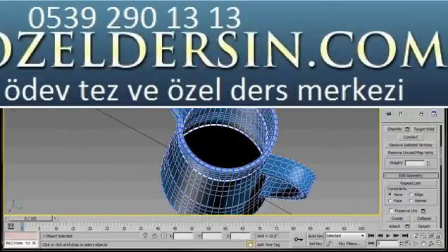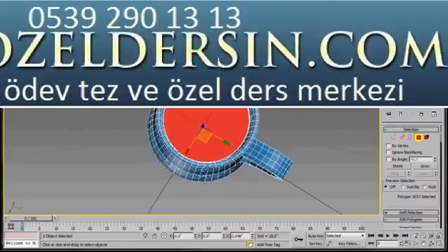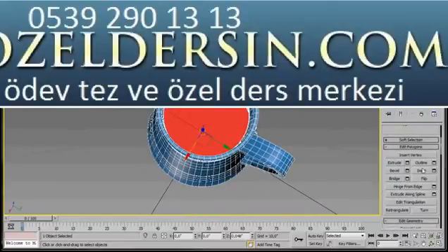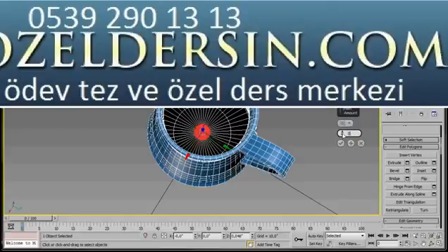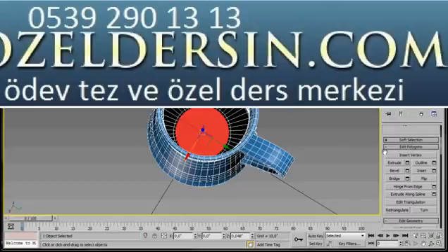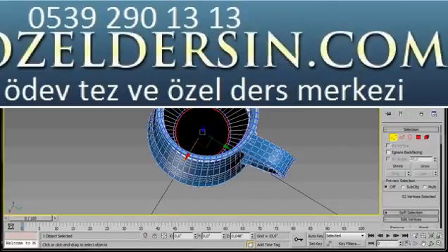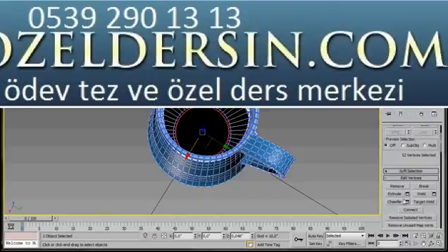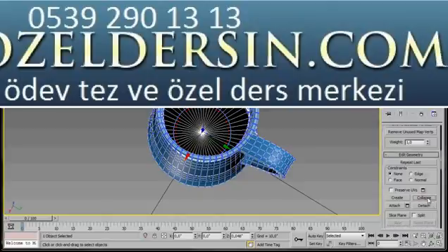Let's select polygon mode and we're going to do the same on the inside. We'll select the inside polygon. Now we're going to scroll down and click on the small settings icon for Inset. We'll start with a small inset first, so just type in 0.05, then press the OK button twice. Now we're going to reselect our settings button, and this time we'll type in 1, and then press OK. We'll do a third one, another small one. We'll just type in 0.1, then press OK. Now we're going to hold the Control key down. We'll scroll up to Selection and select the Vertex mode. This has just converted our polygons into vertices. We'll just scroll down now and press Collapse. Now I'll orbit around.